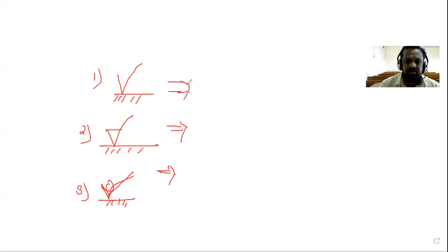Production methods allowed. Yes, when such a symbol is on your surface, I have to understand that we have to produce this surface with the help of any method. There is no restriction for removal of the material. If you have removed the material, it is allowed, and if you have not removed the material, it is also allowed. So if such a symbol is on any surface, you have to understand there are no restrictions.